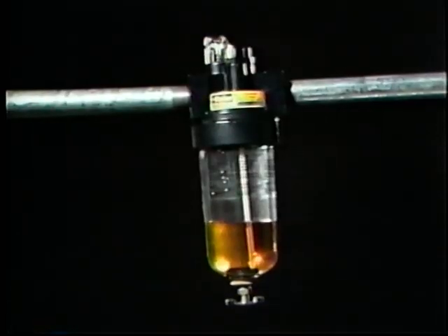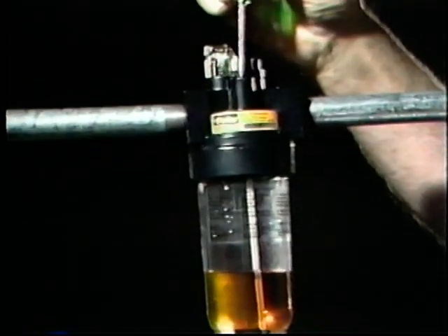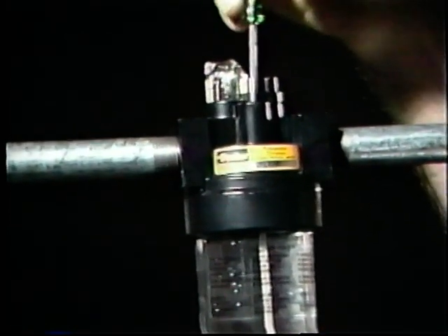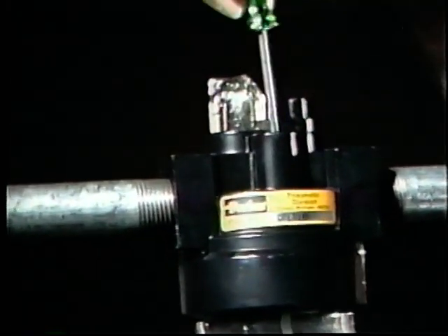Okay, we've said lubrication is necessary to coat resilient seals, reduce friction, and extend the life of system components. However, just because a little oil is good does not mean a lot of oil is better. Many times, lubricators are adjusted so that too much oil is injected into the airstream.